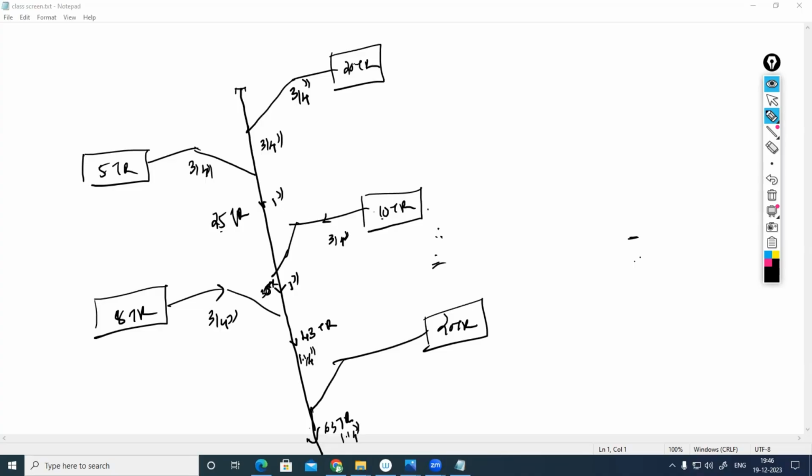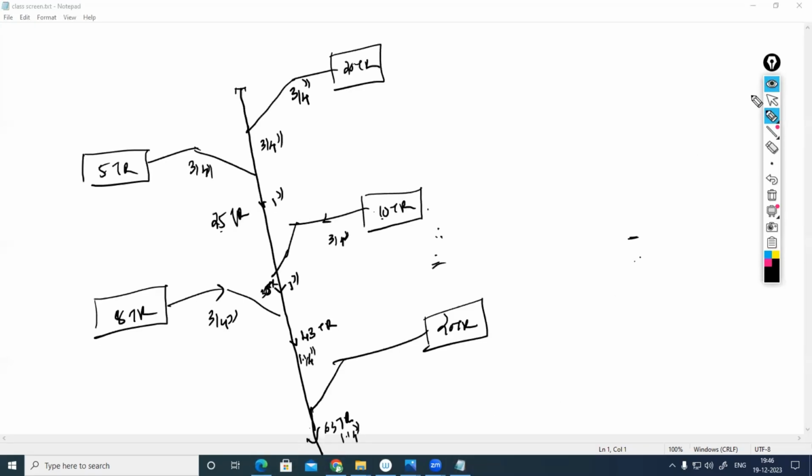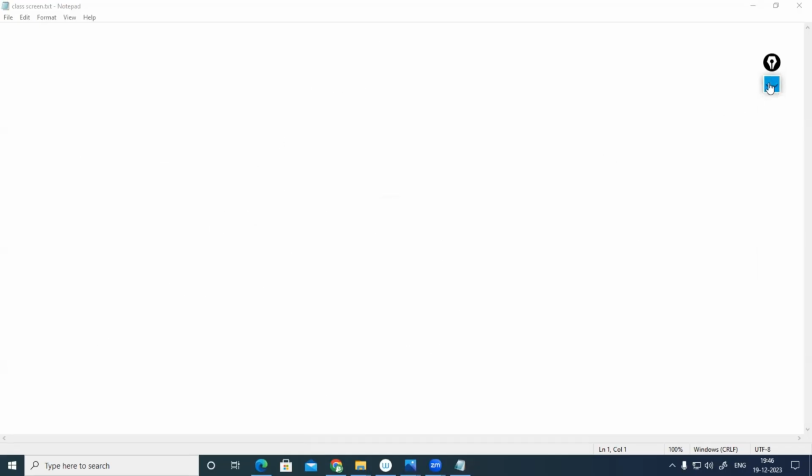Drainage with respect to the DFU we are doing, drainage fixture unit. That table number 701.1 and 701.2 we are using for that. That is different. That in the plumbing classes we can study. Correct. Okay. This is the way, if you are having multiple units above the false ceiling, all the ductable units we will be connecting to the common pipe only. The pipe diameter accordingly we can calculate. Okay. Anyhow, these are in inches only.